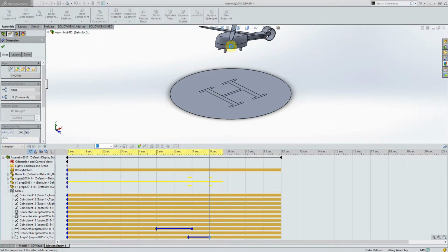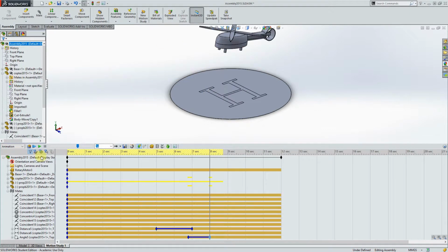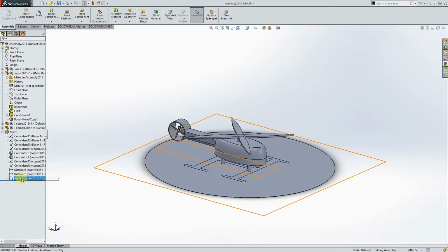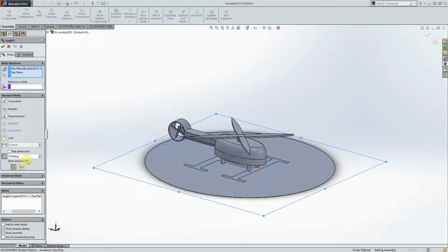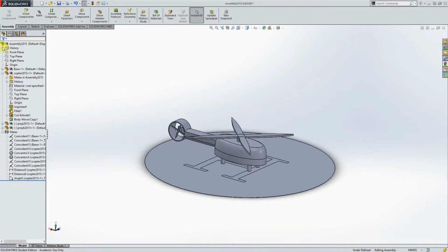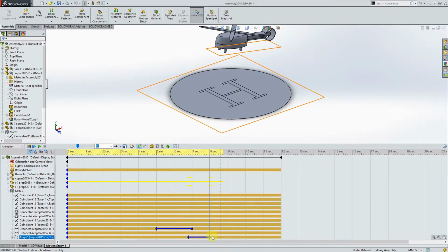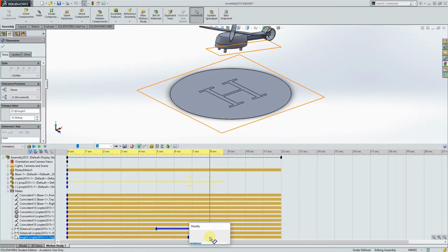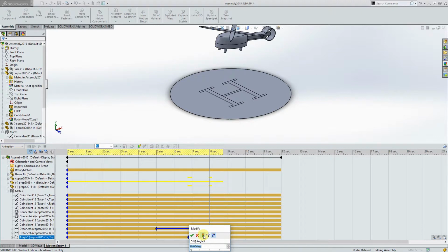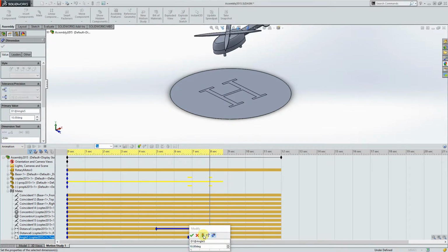And because the SolidWorks motion study does not allow us to use a negative value, we need to go back to our model view, select the angle mate, and flip the dimension. Now if we double click this mate again and rebuild, it now turns the correct way.